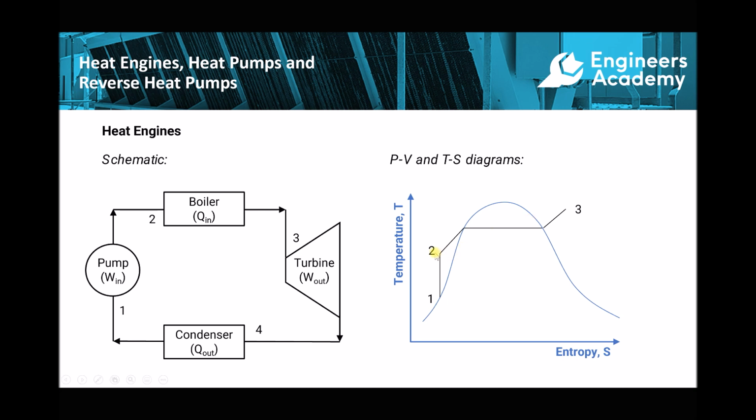So in the boiler, the water reaches its boiling point, it boils until it's all evaporated, and then once it's all evaporated, we continue heating it to create superheated steam. Next, we expand our steam, and once again recall that here we're going to have a mixture of water and steam, or a wet vapour if you like. And next, we're going to convert that remaining steam back to water.